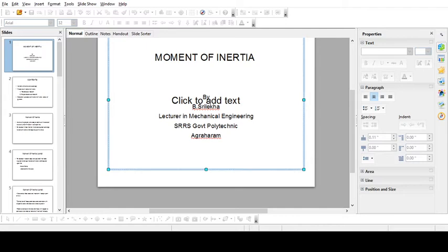Now similarly, if I want the moment of inertia about the Y axis, then parallel to the Y axis you will have the centroid axis, and again IAB is equal to Iyy plus A into H square. There H will be the horizontal distance. Here H is the vertical distance and their axis will be vertical, and here we have the axis as horizontal. So like this we'll be doing it.